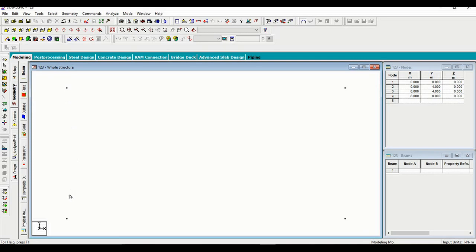You should not randomly jump from 1 to 3, 3 to 2 or 4 to 2 like that. You should go in a manner. So it is from 1 to 2, again 2 to 3, next is 3 to 4. Like that you should join the nodes. Then only the results will be proper, or else it is a mistake.